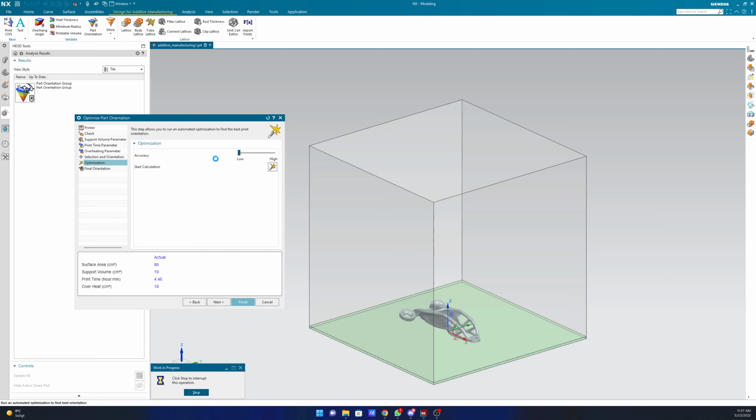If you go low here, Netfabb does it so much faster, yes, and so much better. But this is more important because it considers that the part is connected to the build plate, which is more important than the volume it's consuming. So if you use Netfabb, it only considers the volume, but not the area on the build plate. So your parts may be hovering over here somewhere, only connected by supports to the build plate, and that creates differences in parts. But in this case, if all your parts are connected to the build plate, it will have the same properties throughout the height.